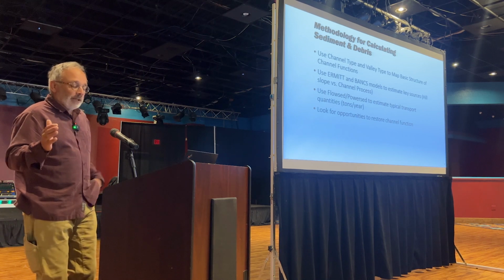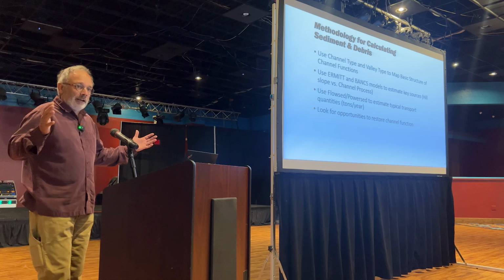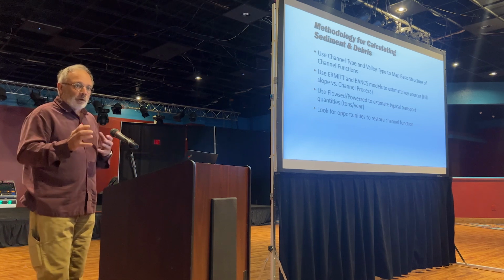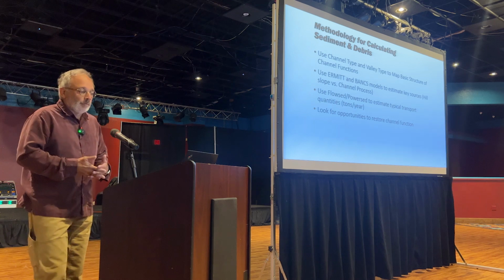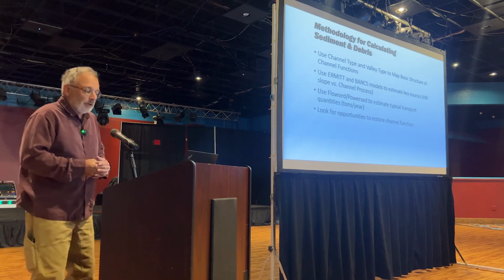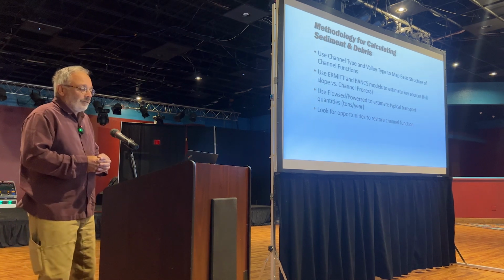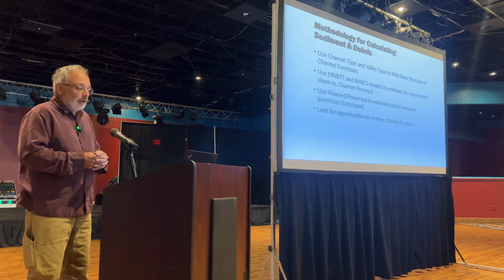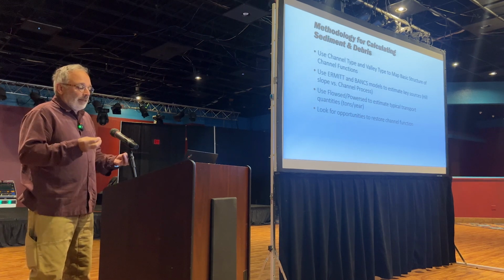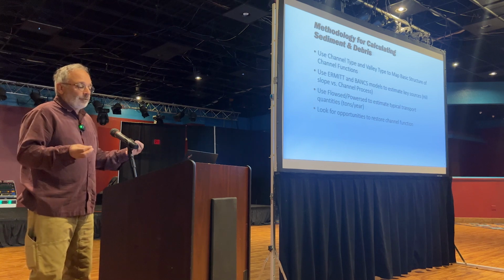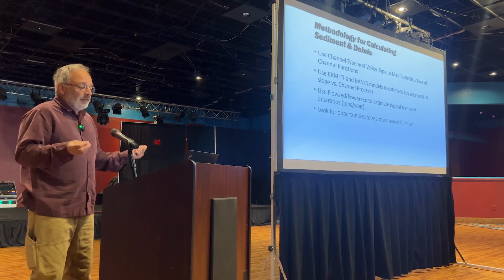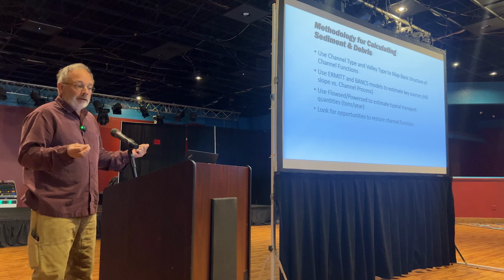So it's a way to really quickly whittle down a big area and a big problem into smaller chunks that you can look at. Then you can apply this ERMiT model, which is a web-based model that's easily available on the web, and you compare that to your BANCS model, and I'll talk a little bit about that, to estimate those key sources, whether they're hillslope or channel processes, okay?